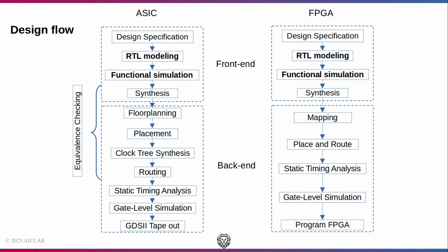We only want to make sure that our design behaves as expected. The next step is synthesis. Synthesis transforms our RTL design into netlist of logic gates based on technology library and user constraints.